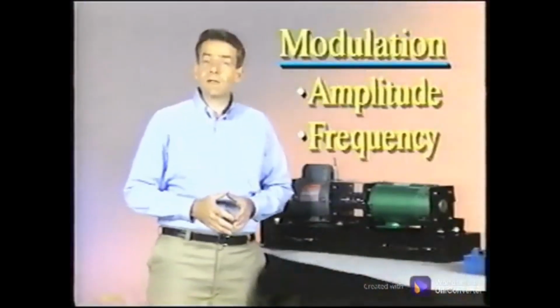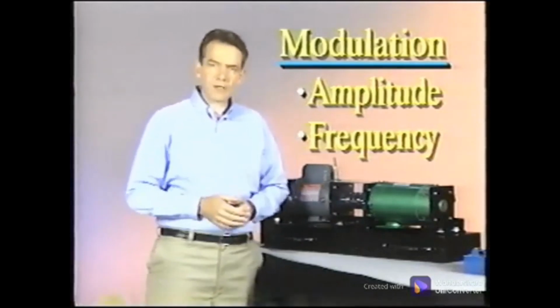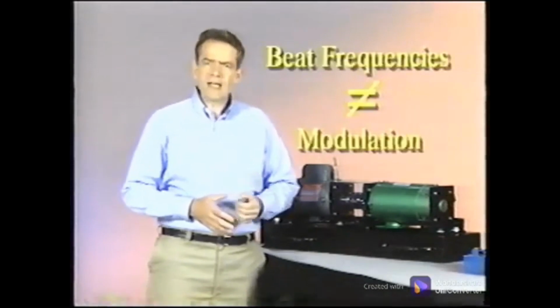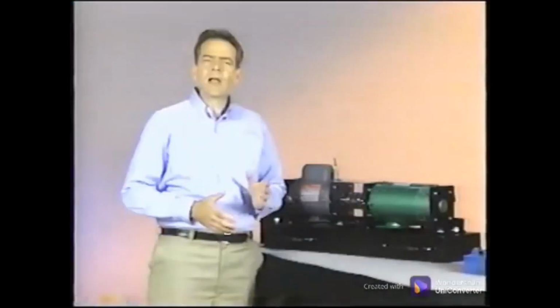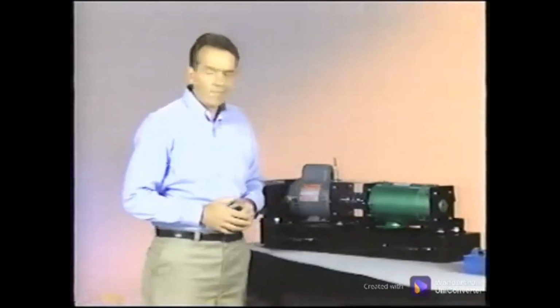Two types of modulation seen in vibration analysis are amplitude modulation and frequency modulation. A third phenomenon, beat frequencies, are often mistakenly thought of as modulation. Modulation is the product of two frequencies, a carrier frequency and another frequency, whereas a beat frequency is two primary frequencies that add to and subtract from each other. Let's examine the waveform and spectral characteristics for each of these phenomena.